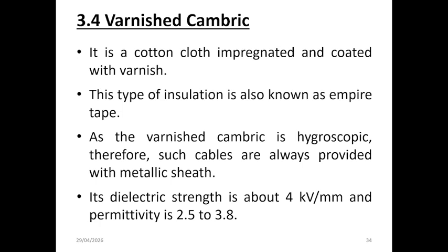Since varnished cambric is hygroscopic, cables using this insulation must always be protected with metallic sheaths to prevent moisture ingress. Its dielectric strength is around 4 kilovolt per millimeter, and its relative permittivity ranges from 2.25 to 3.8.